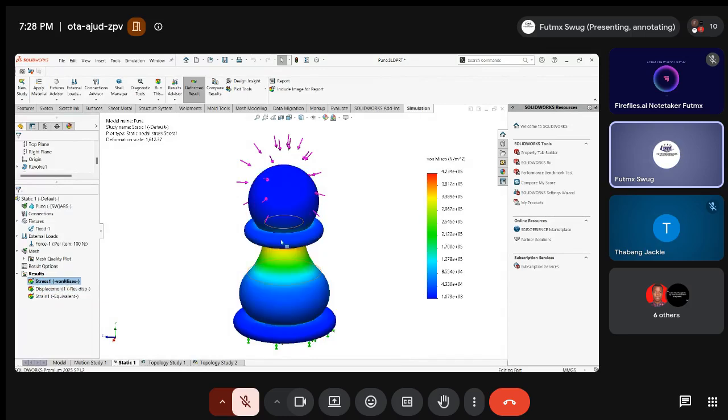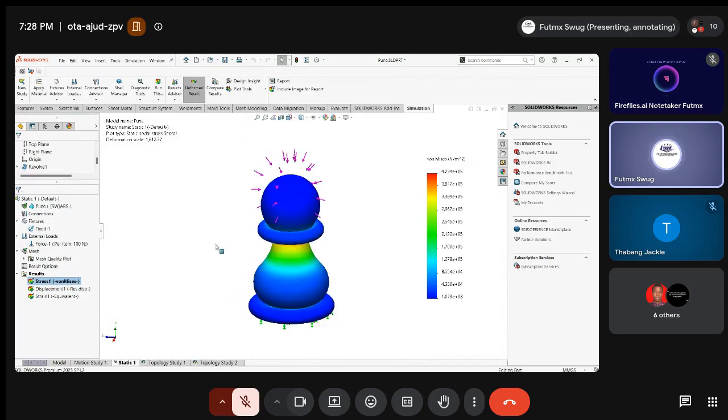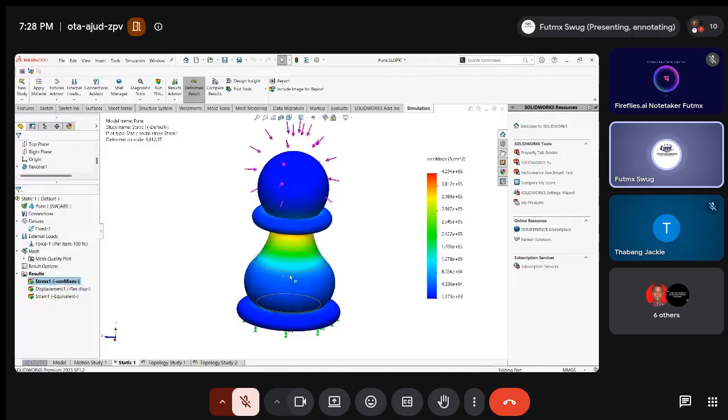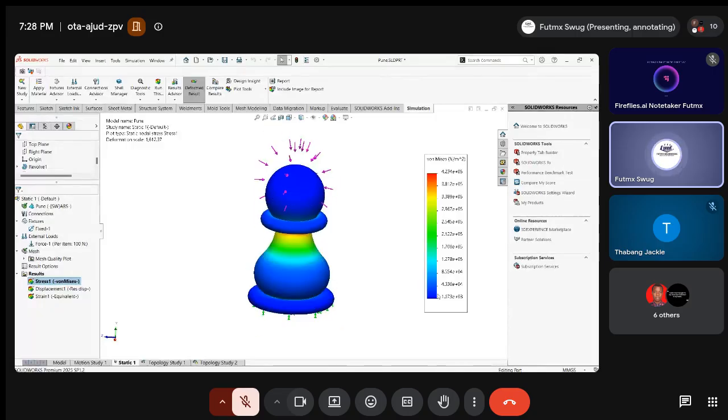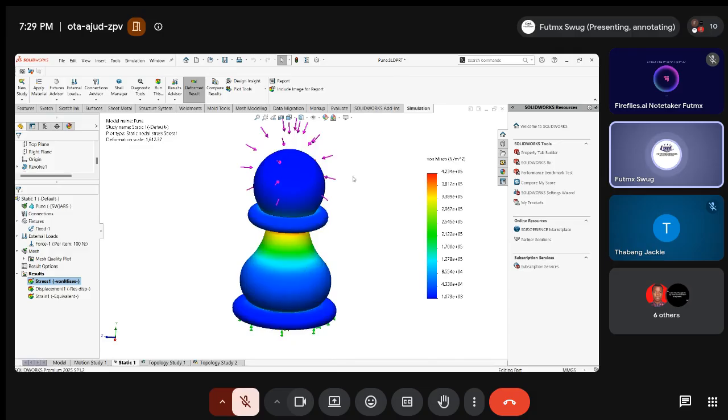Okay. So if you check the stress, this is the stress analysis. When you compare the von Mises stress to the actual material allowable stress, you discover that this particular part can still undergo the applied load without totally deforming. So that was what we got from this analysis.